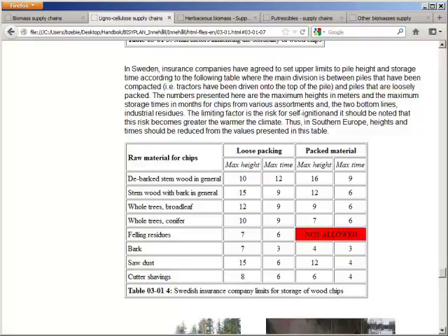It will also affect the quality of the fuel finally available in the stored pile and the fuel that you are able to deliver. You will have to be very, very careful during storing and plan the storage very carefully so as to allow for low storage heights and the shortest possible storage times. But you will not be able to avoid storage totally.